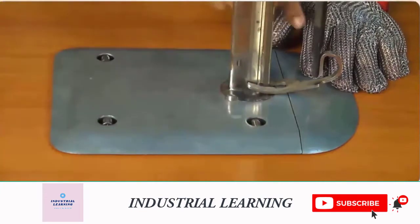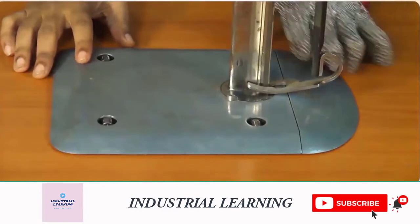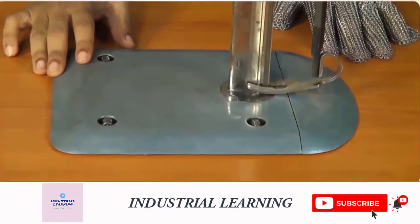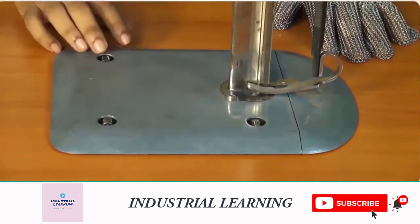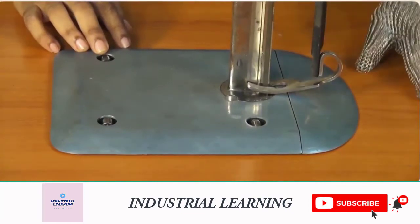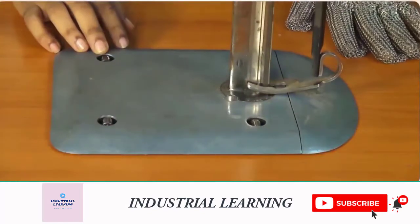One is the squarish part, the other one is the half moon part. This half moon part is sloped in nature because when there is a fabric lay to be cut, when you push the machine into the lay, the bottom ply will come above the slope and gets lifted up for cutting.